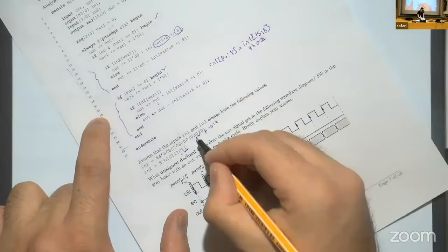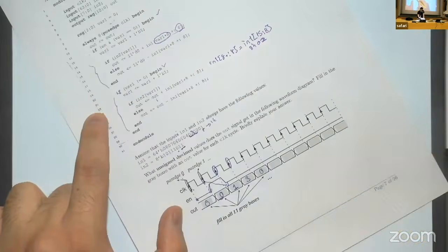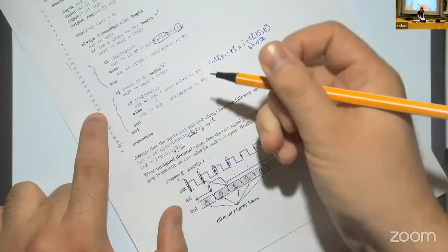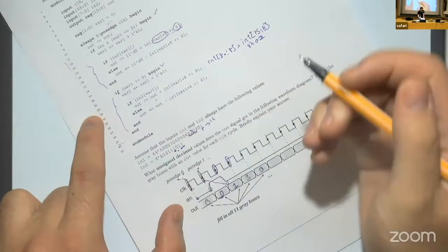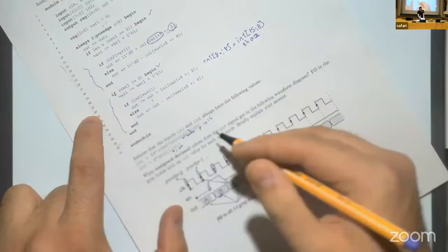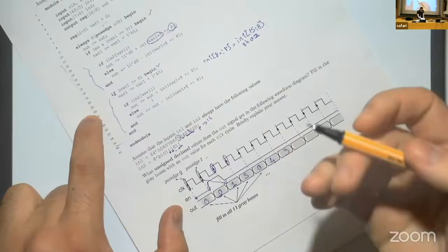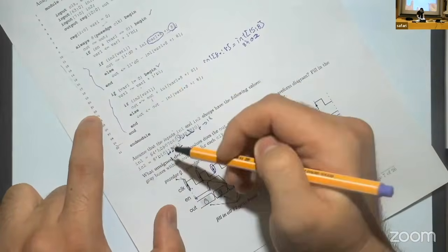We increase the var1 and make the out 15. Now in the next cycle, we execute again the always block where var1 is now 6, and the bit is 0 in the in2. Which means that we need to perform subtraction here. It was 15, and this one is 7, makes it 8.